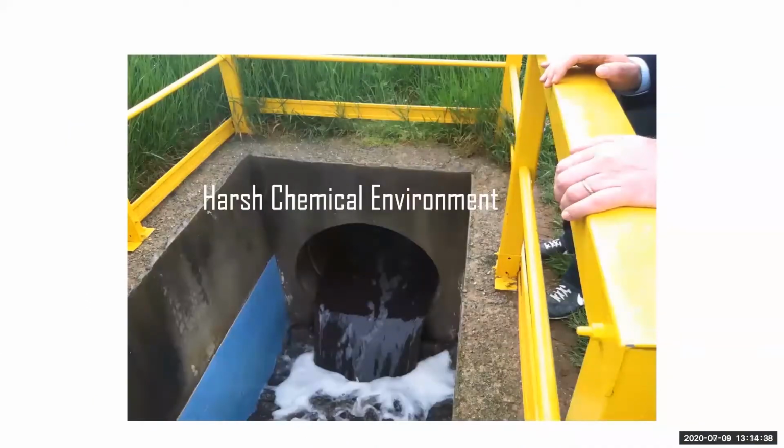So let's look at some difficult applications. This is one that was actually Istanbul, Turkey. Very challenging location. Water is free falling into that channel. So a standard unit wasn't going to work very well because it would have tried to measure level right at that foam part, but try to measure the velocity into the channel. So that one had to be, we had to do some modifications to a unit.